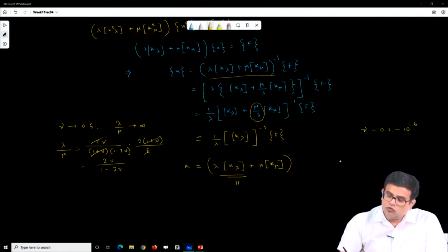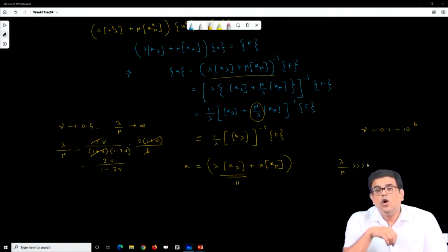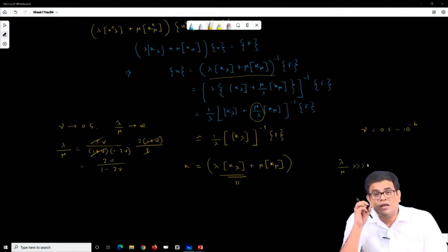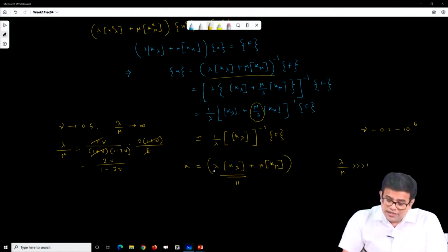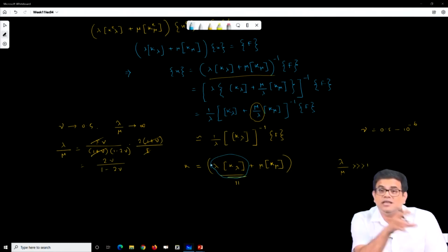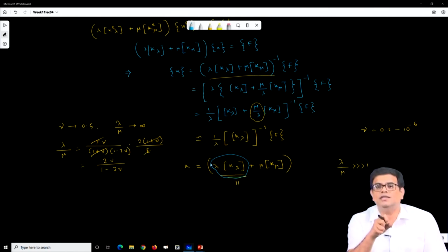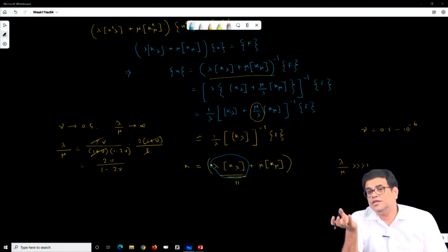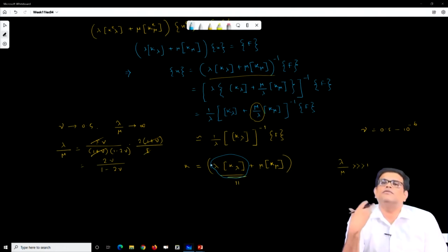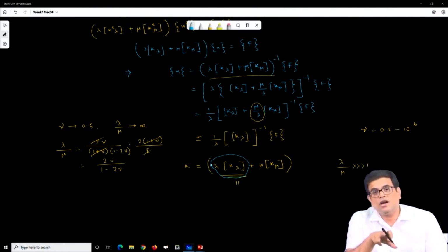So, basically how we define nearly incompressible material is that the lambda by mu ratio is very large. That means this component of the stiffness matrix acts as a penalizer. Since the volumetric deformation will be 0, all the deformation will go to 0, which is not correct.